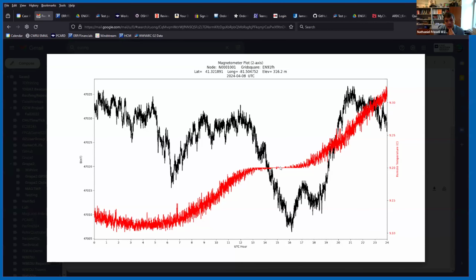Yeah, so I was wondering, do we know how much of a temperature change is really going to have an important effect on the magnetometer readings? I do not know what the TempCo is of the magnetics in the magnetometer. And I'm not sure they published them yet, because when they originally came out with it, they said there was the 0 TempCo, which then we proved to them it was more of a very good temperature sensor. And then they said there is a TempCo, but I have not seen the spec for it yet.